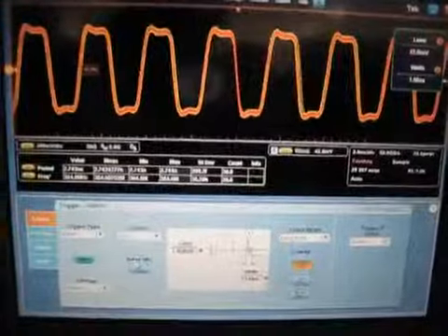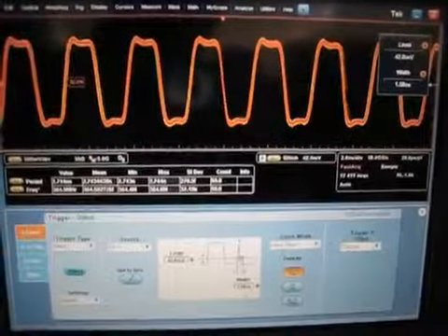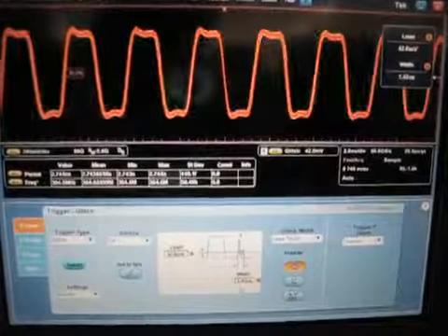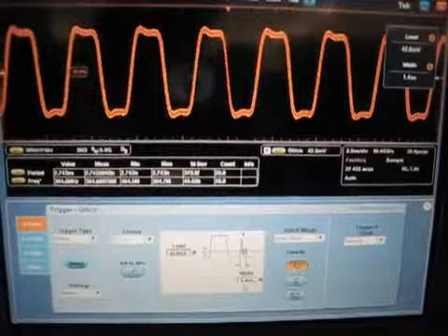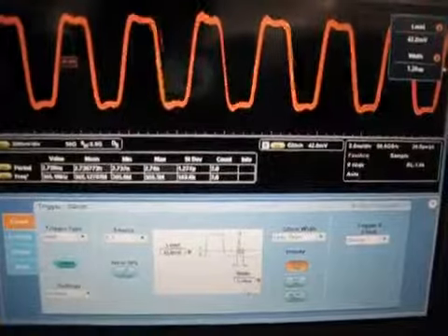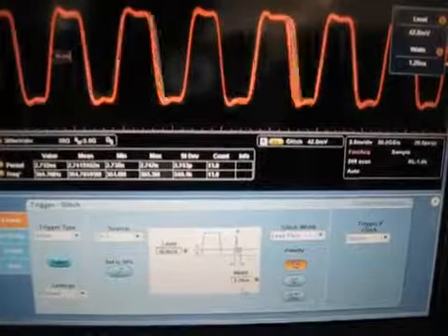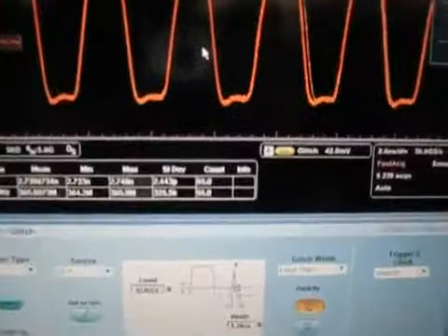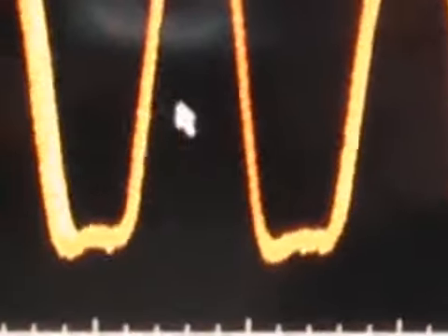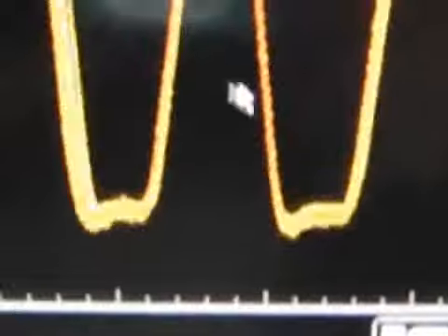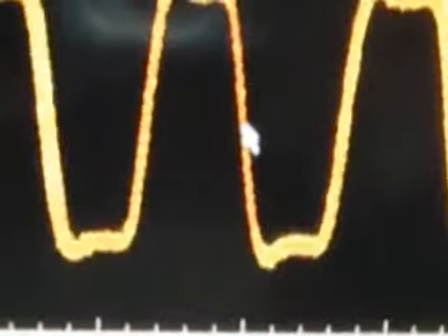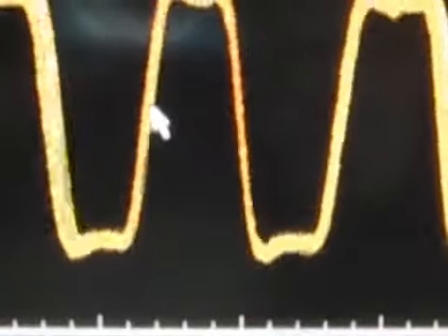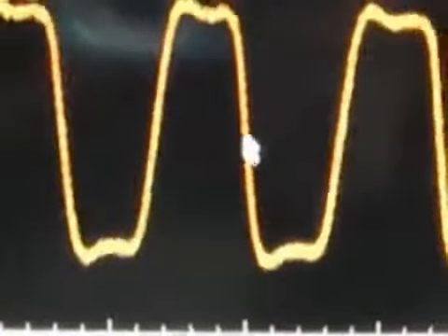We only trigger on the positive pulse width. Let's decrease this pulse width a little bit. Right now I'm using 1.4 nanoseconds. If I continue to decrease this value, finally you will see on the normal DDR signal there's some intermittent short positive pulse. This is the trigger point. We can see this is pretty outstanding, much narrower than the negative pulse width, right?